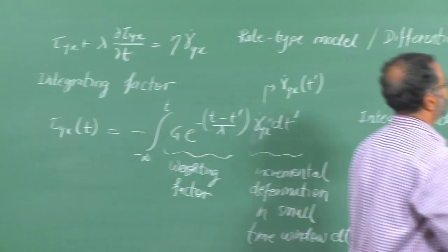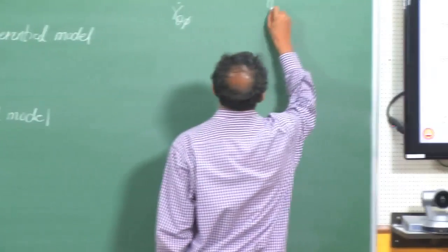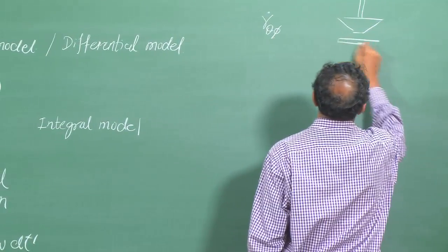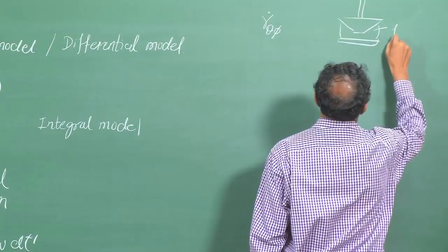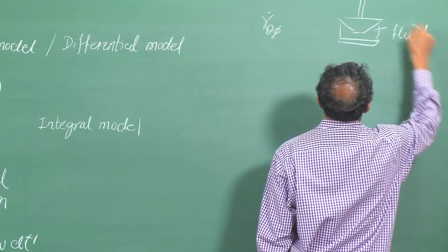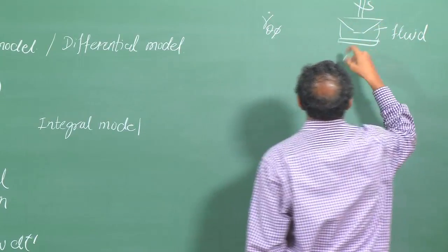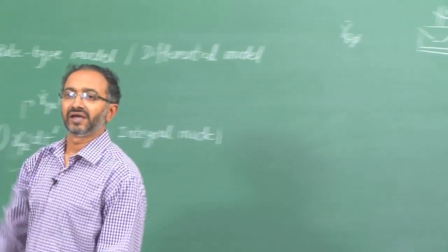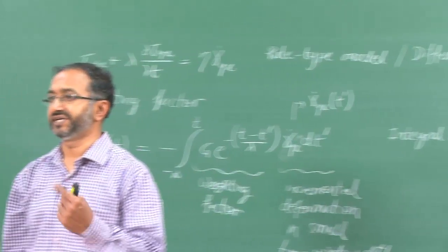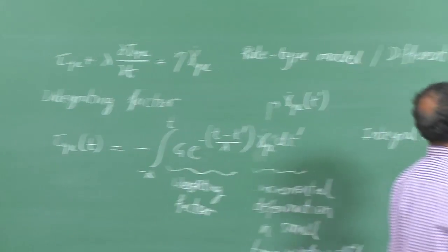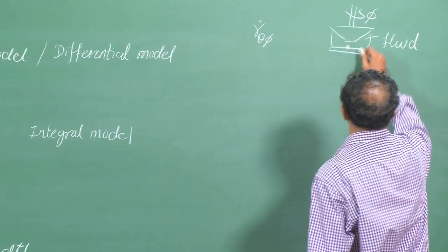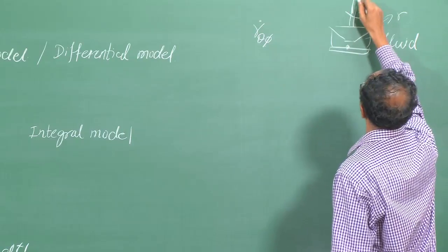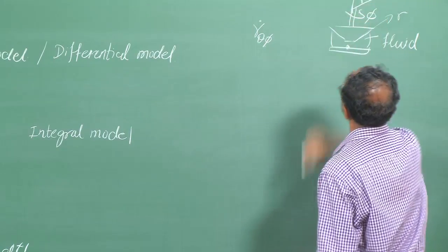And in this case what we have is a cone and a plate, and fluid is in between, and the cone is, let us say, rotated. So therefore this direction is phi, the rotation, and the shear direction is theta. So we use spherical coordinates to describe this point, with this as the origin and this going out is the radial direction, and then the angle with respect to this axis is theta.